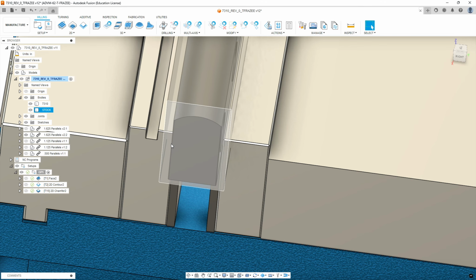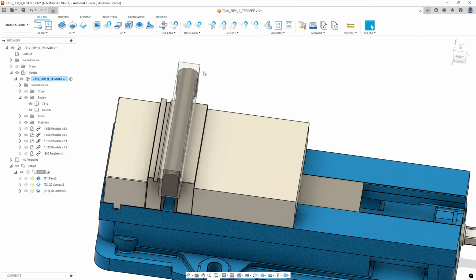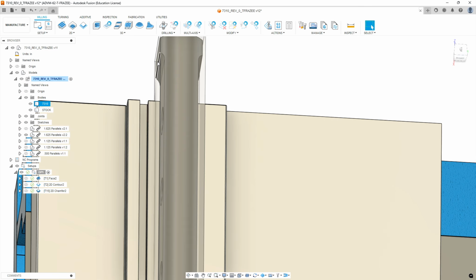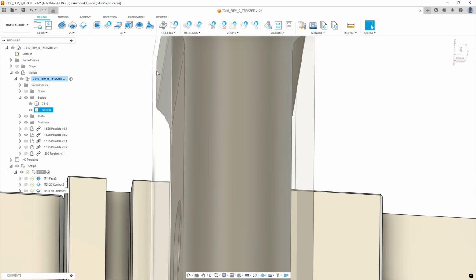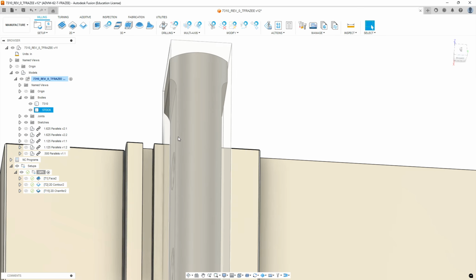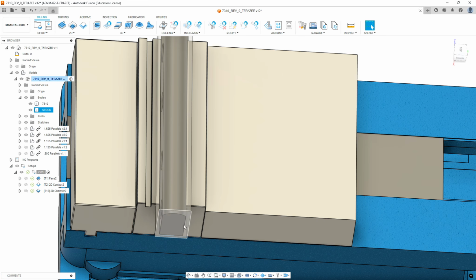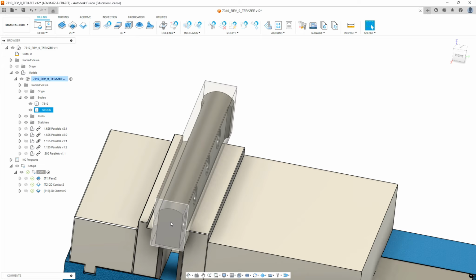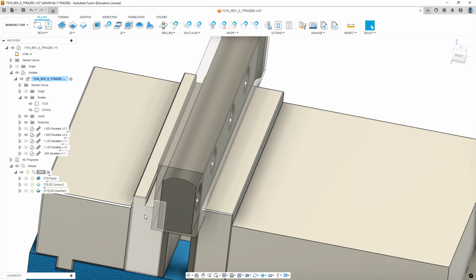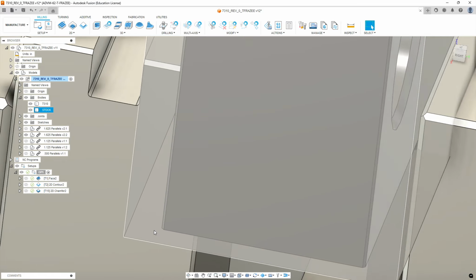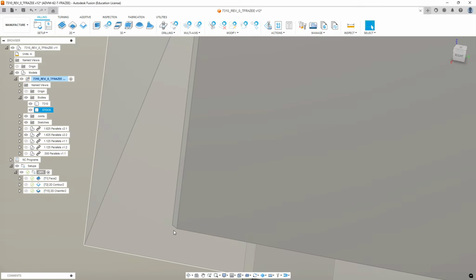But we actually want to clamp onto this edge that, even if we go off model box point, is basing it off a corner that's out here because that's the extent of the model. In this case, we want our origin to be placed on the fixturing in the corner. And what we have is a chamfer here that won't allow us to select that corner. We can do selection, but we need to create something that we can pick on there.